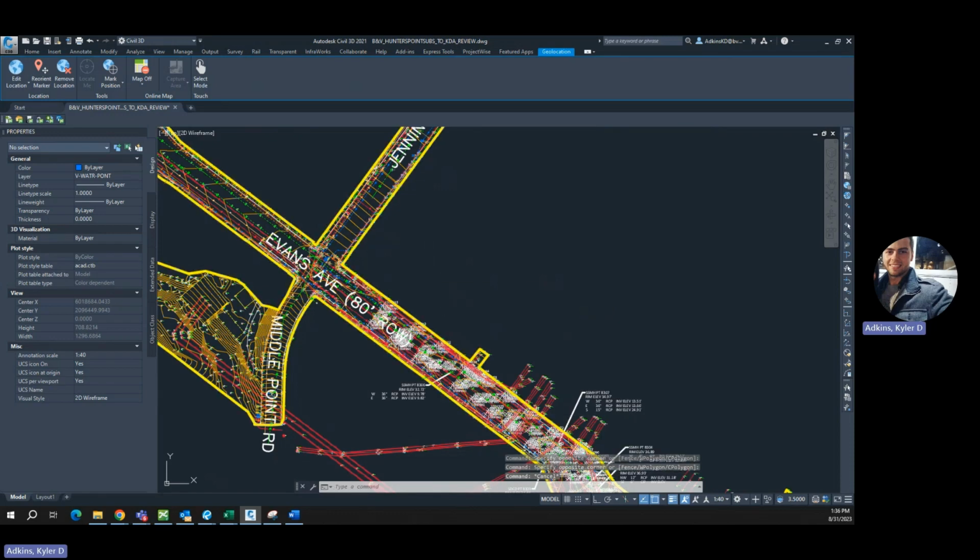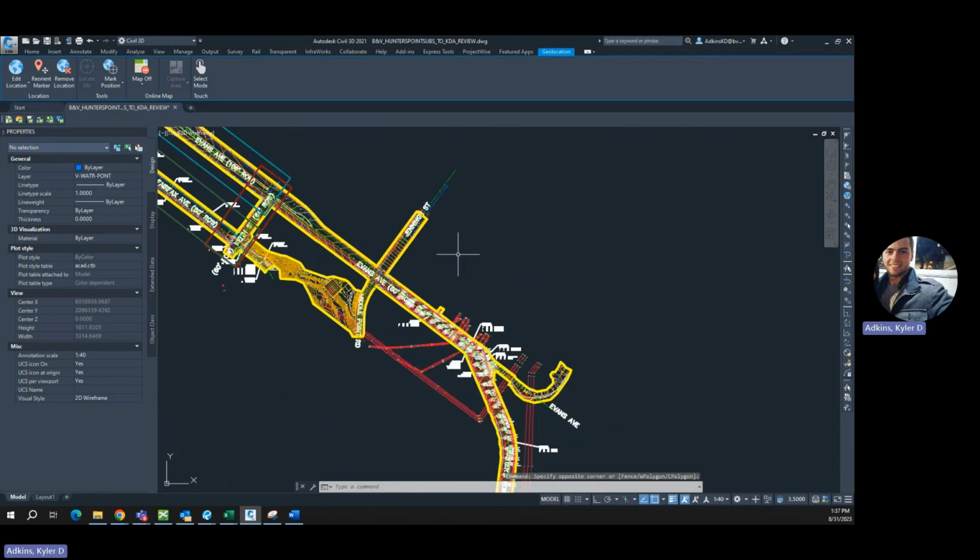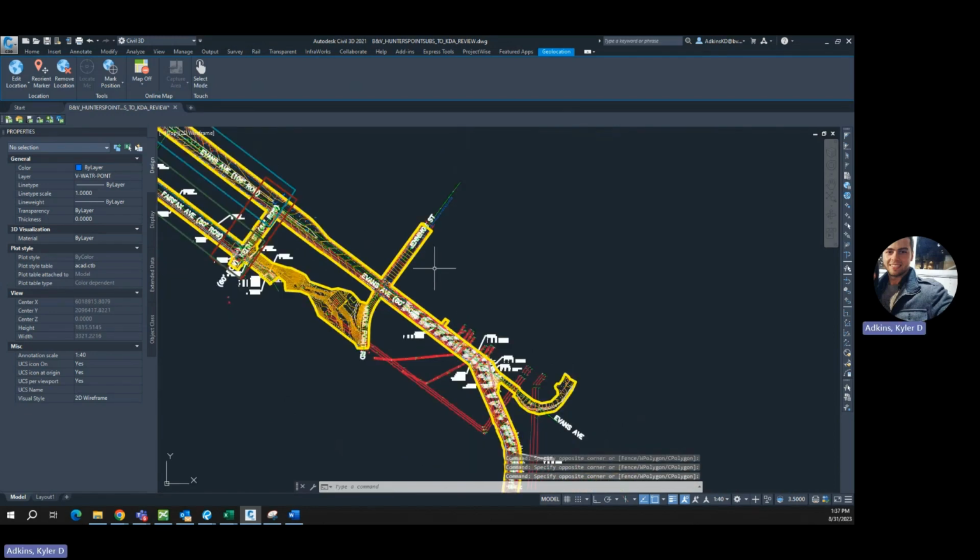But in the event that you have more than 50, you'll want to report that back to the surveyor and request that future files, when they're sent over, should be purged before they're sent over. A lot of times that's one of those little things that doesn't get caught and causes a lot of headache down the road because your file ends up getting bogged down and corrupt and very hard to work in. But yeah, that's the quick and dirty of doing a survey check.